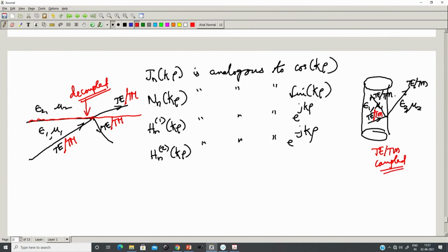Okay. So, as a result of this, if we want to characterize the cylindrical boundary in terms of reflection coefficients, we have to go towards the reflection matrix instead of the reflection coefficient, because here the reflected field is not described only in terms of the reflected TE mode. If you talk of the reflection coefficient, the question immediately arises, are you talking of the reflected TE mode or the reflected TM mode? Therefore, in order to describe this complex behavior for cylindrical guided wave structures, particularly cylindrical dielectric guided structures, we have to take recourse to the reflection matrix instead of the reflection coefficient, which characterizes the planar medium. So, these are the inherent distinctions between the planar or rectangular and the cylindrical dielectric to dielectric interface. Okay.